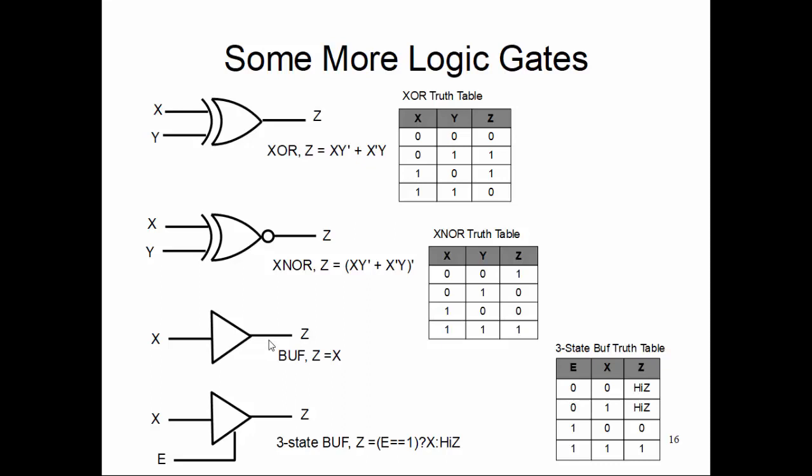Okay, so let's say you are driving far away gates, then what happens, since it is all electrical and a physical phenomenon, your signals start degrading, your logic high or logic low starts degrading, and it may even become inverted through the electrical effects, right? So you can think of the buffer as an electrical signal amplifier. It just picks up a logic signal, amplifies it, and makes sure it goes as the same logic into the next stage. So if two logic components, one driving another, sit far apart, we usually insert a buffer to make sure your logic value transfer is good enough for the target device.